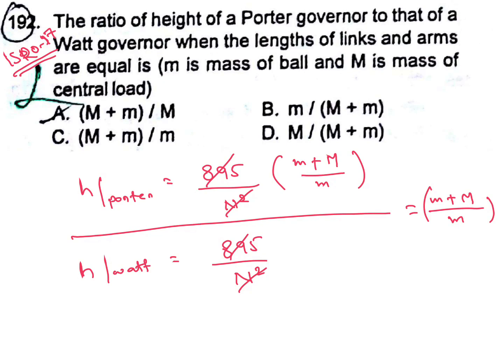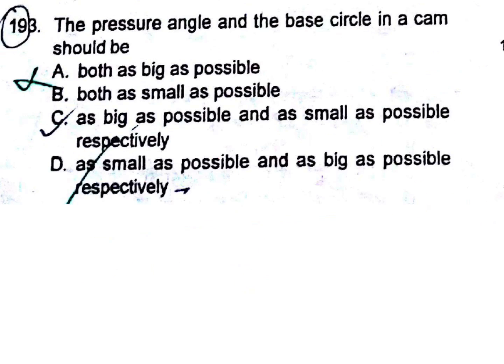The pressure angle and the base circle in a cam should be: pressure angle as small as possible and base circle as big as possible.